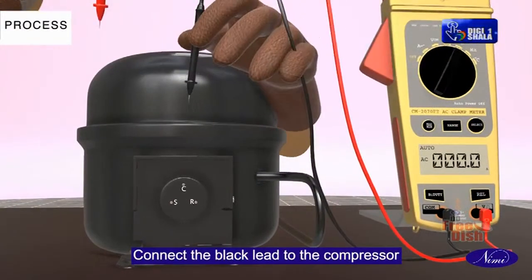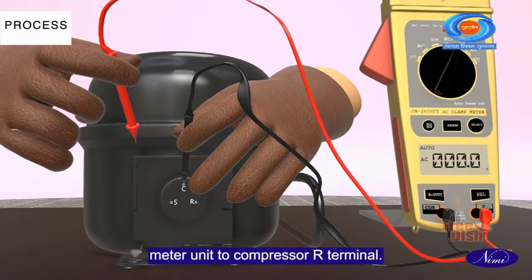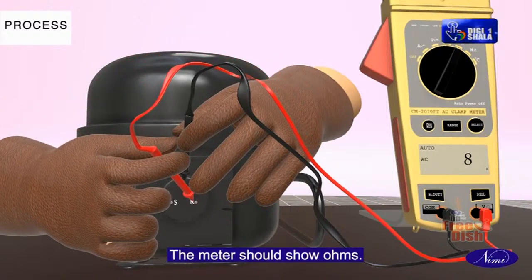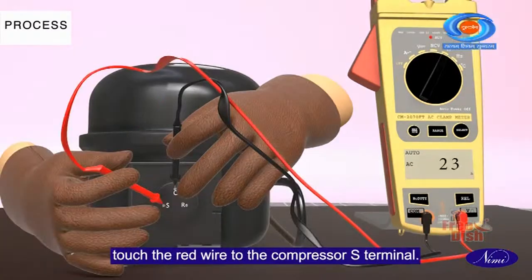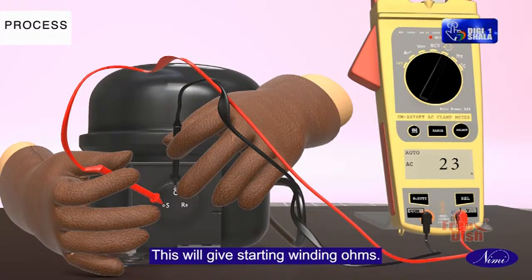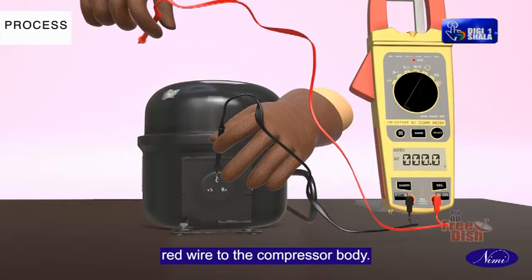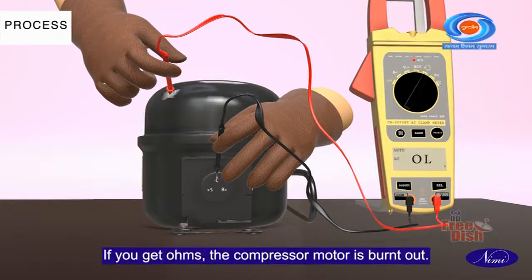Connect the black lead to the compressor top terminal C and the red lead of the meter unit to compressor R terminal. The meter should show ohms. Without removing the black lead, touch the red wire to the compressor S terminal. This will give starting winding ohms. Without removing the black lead, touch the red wire to the compressor body. If you get ohms, the compressor motor is burnt out.